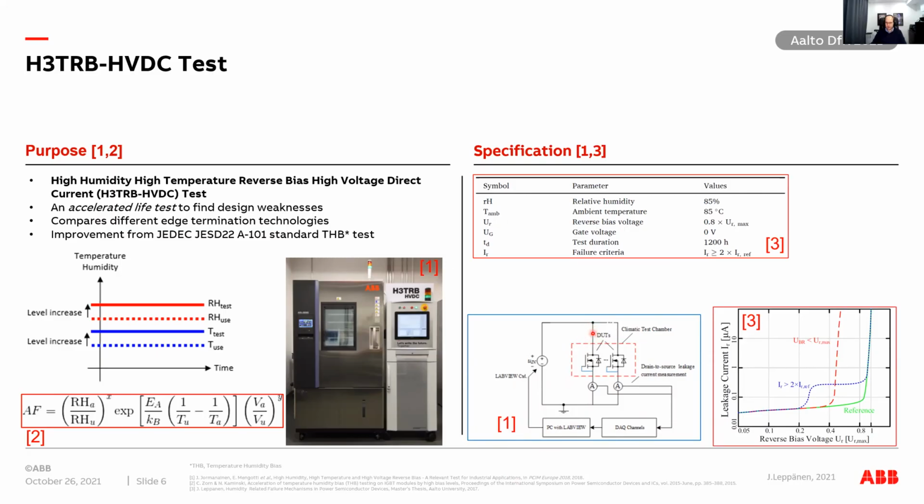It's not actually shown here that we have this capability nowadays, because in this early paper that was published a few years ago, we didn't have it, but typically we have relays or MOSFETs controlling the circuitry so that we can cut each sample off separately, because eventually they will be in a short circuit if there is a failure.